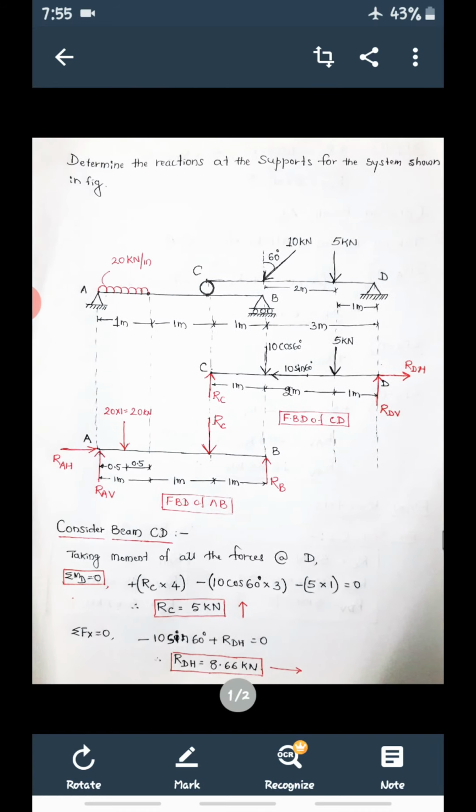The important thing here is when you get beams like this, 2 beams. Till now, in all the previous problems we had only 1 beam, and we used 3 equations. Here also the same concept will be applied, but we will consider each beam separately. While drawing the free body diagram, we draw it as given in the diagram. So this is CD, and below this you draw the other beam, with point C, point D, and here A, and below this a roller, and below this support B.